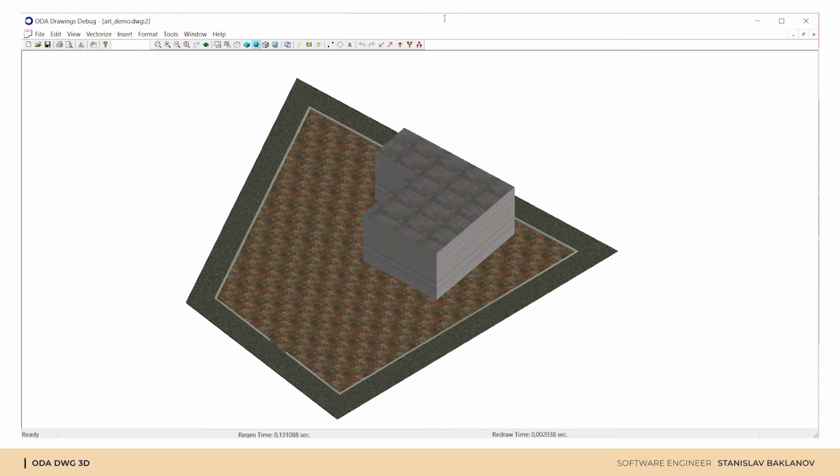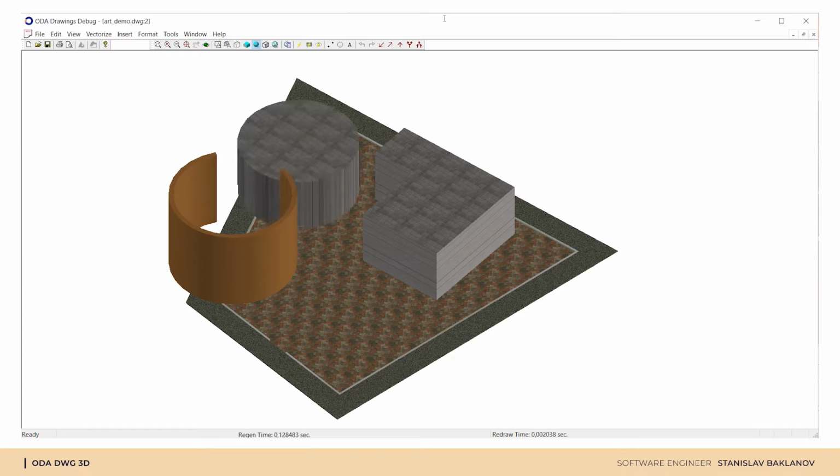Now we create a rectangular region, make revolve operation with custom angles to build a cylindric wall. We perform another subtraction between a cylinder and a box with materials, and unite resulting solid with the cylindric wall, and with the first solid body.